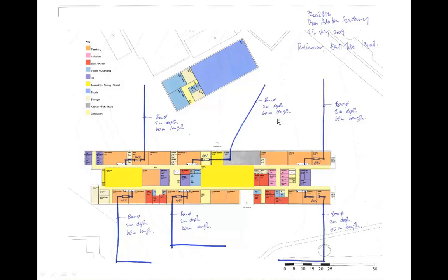Now what you're doing is, when you pull the air in, as it is passed along that concrete pipe which is buried in the ground, in winter it's getting gradually warmed up by the earth, and in summer it's getting gradually cooled by the earth. So it is a fantastic means of getting some free heat in winter and some free cool in summer. We have this term cool, meaning the opposite of heat. But it means basically getting some free cooling in the summer. It's a very, very good system.